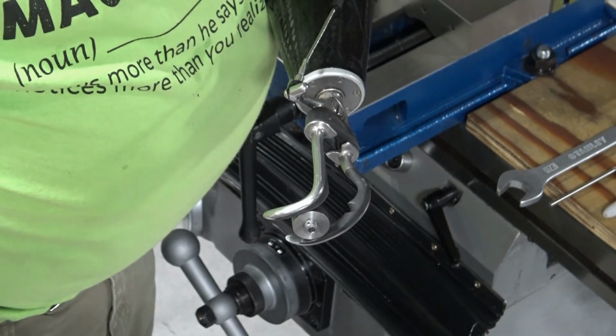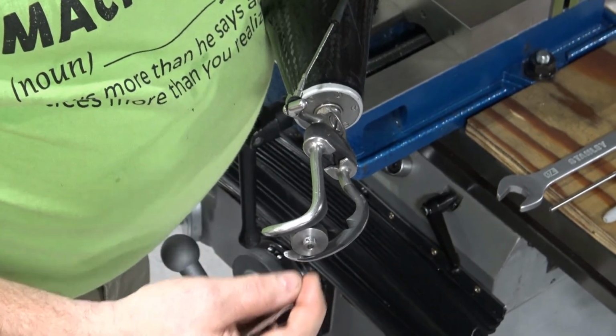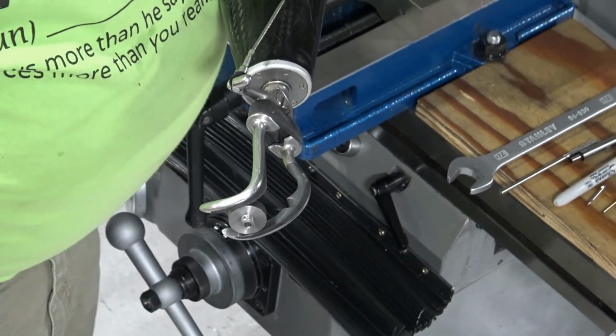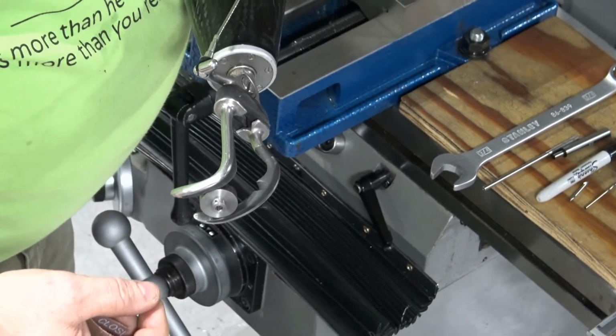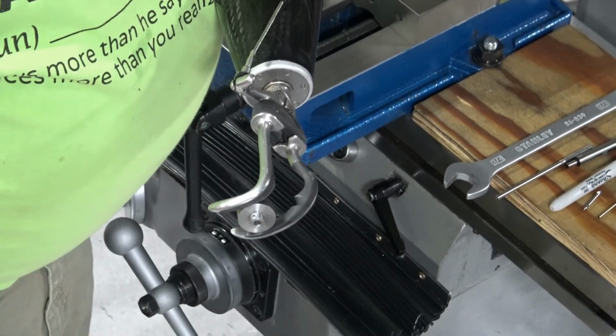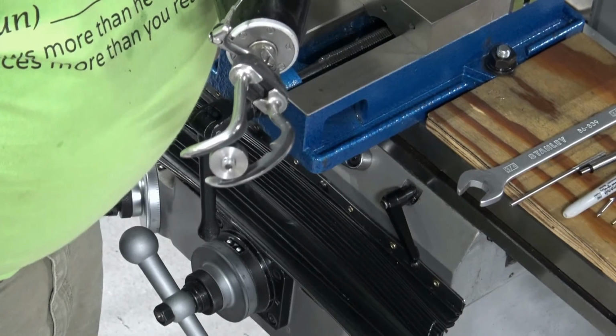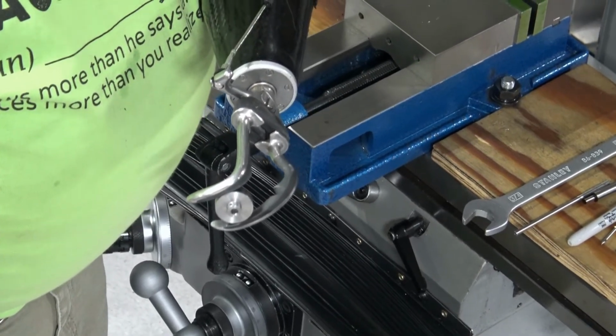At that point in the game, the only thing I would like to do is take my 3/16 or number 2 center drill and double check my slip fit and make sure that I have the clearance that I want. As long as I use the 1885 reamer, I should not have any problem. So now we're going to move on to putting our offset pin in our crankshaft.